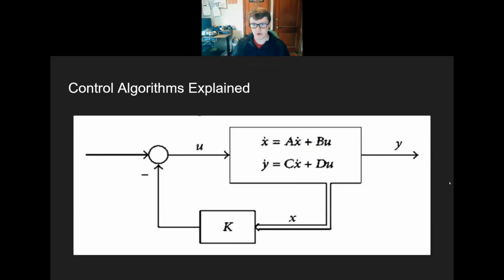There's a third type of controller. There are these full state feedback controllers, and specifically the thing on the custom quadcopter that you might run into with these is the LQR controller. A full state feedback controller basically takes the full state of the system and feeds it into a dot product with a K vector or K matrix, depending on how many actuations you have. That then sends out your actuations for the next step. This is a much more complicated, much more advanced type of controller.